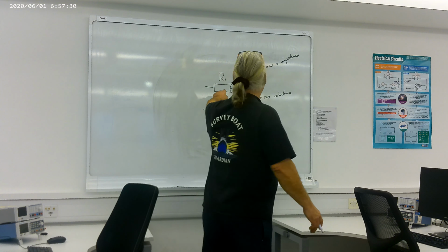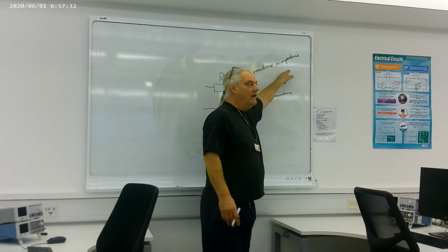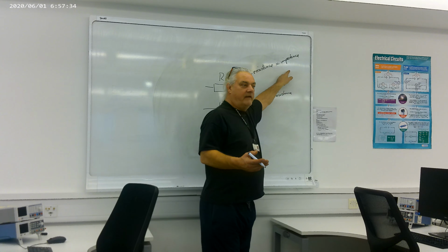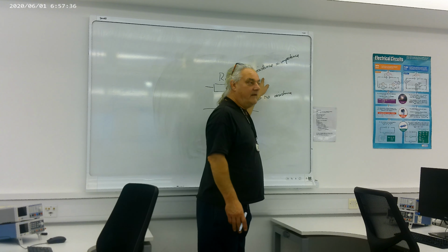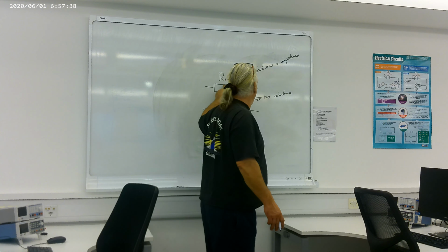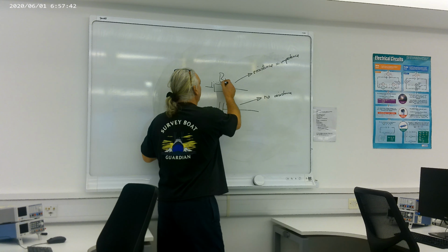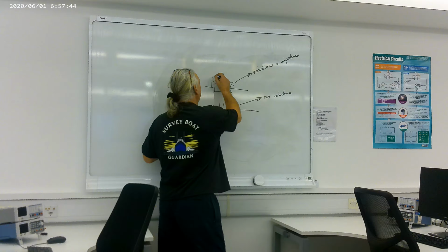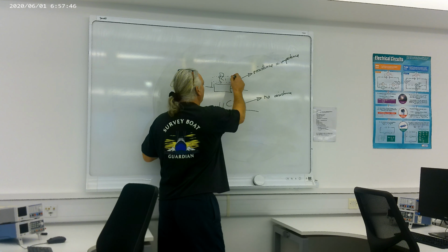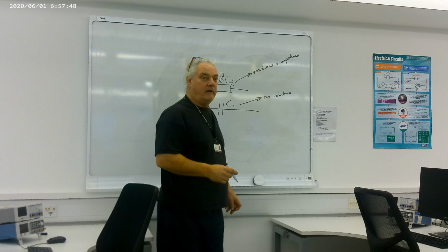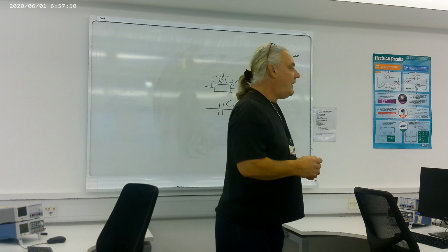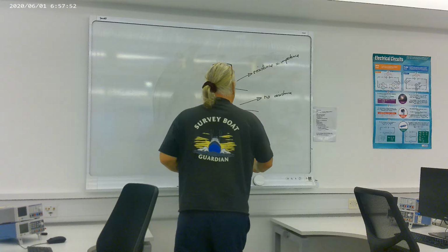So can a resistor have impedance? Yes, it can. But for a perfect resistor, it's exactly the same as its resistance. It will have, unfortunately, a little bit of capacitance, a little bit of inductance. This is where circuit theory gets really complicated and quite advanced.